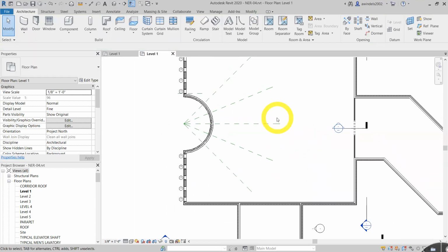We're going to use the Align tool, which is a very important tool in Revit. We've used it a couple of times, and it helps us just line things up to a source we know is good and take the object that we need to align to it. So the big deal with the Align command is we have to select the object we want to align to. That's kind of the key thing to think of. And then we align to it. So once you get that thought out, you'll be a lot better off with the Align command.